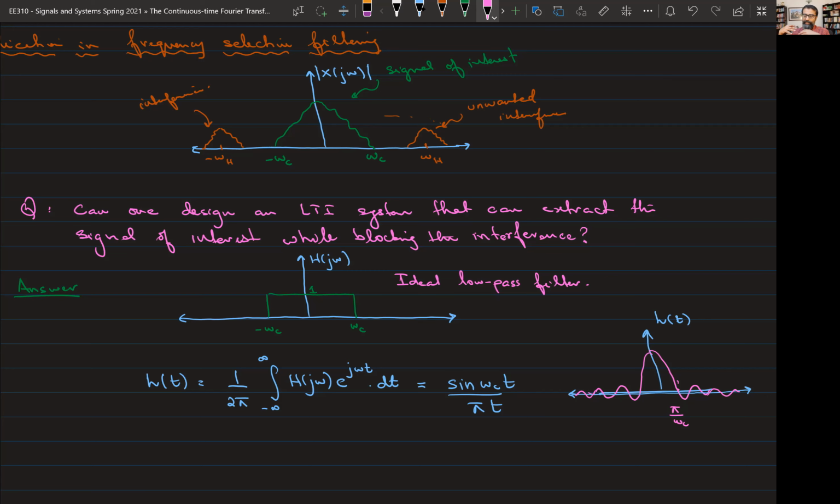So filter design is a whole different dimension, something we don't have the time to dig into, but I just want to touch on some things here. Practically, you use RC and RLC, and then multiple stages and so on and so forth, first order, second order, third order, and higher order. So it is because of that convolution property that we can design these frequency selective filters, to cancel things out, to extract things out, and do a lot of other things. I recall saying something about equalization a while ago.